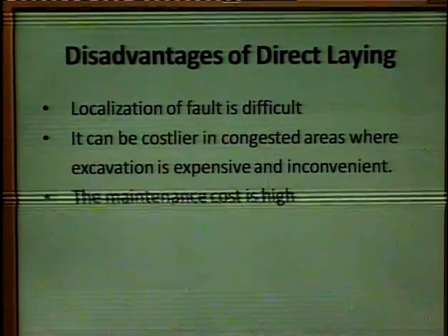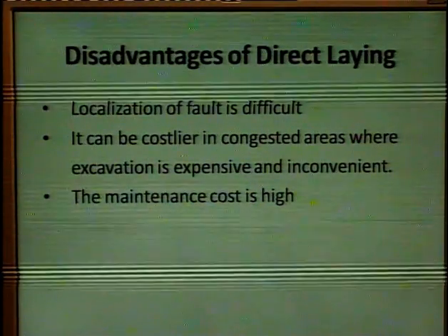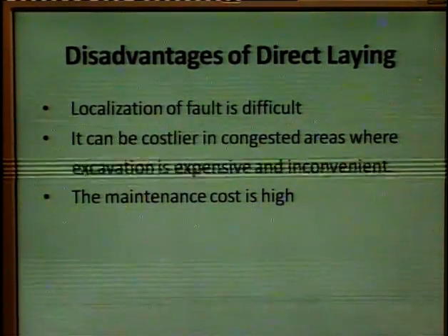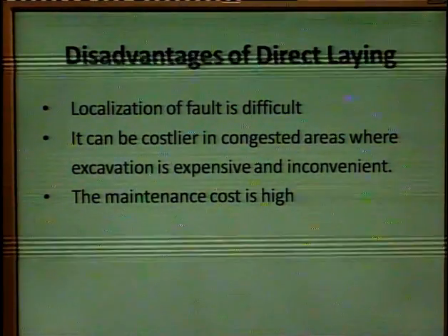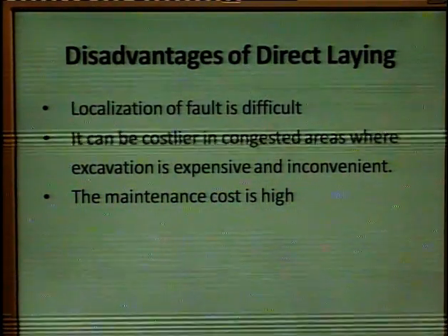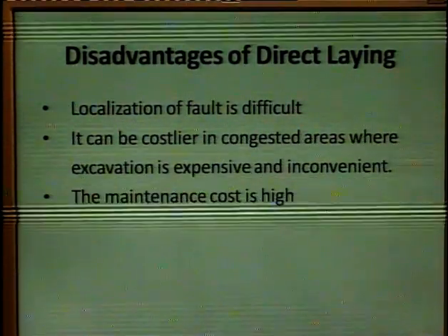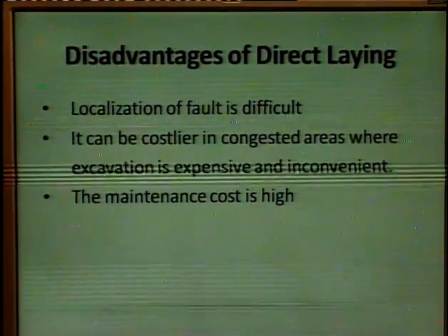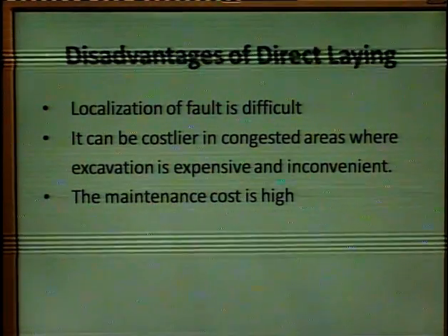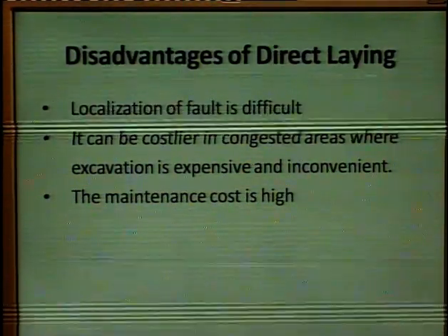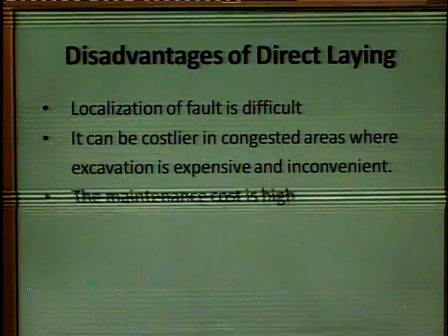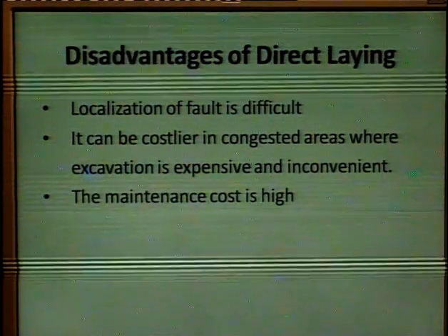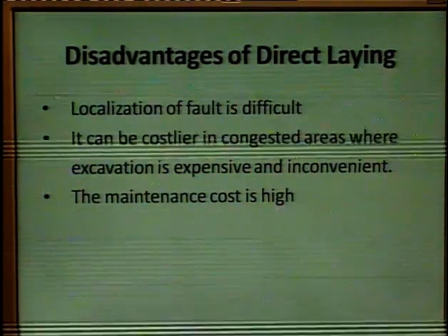Then we have some disadvantages of this direct laying. First, the localization of the fault is very difficult. In case there is any fault in the cable, we have to dig the complete system, then we have to locate the fault, which is very difficult.